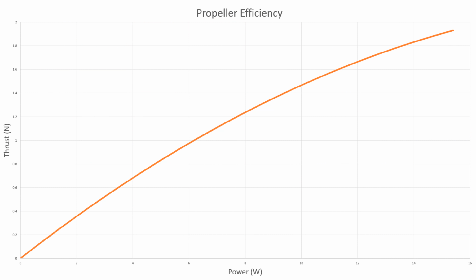And if we look back on the propeller efficiency graph, at low thrust values, it produces about 20 grams of thrust per watt. But at higher thrust values, it only produces 13 grams of thrust per watt. So as the thrust is increased, the propeller efficiency decreases, probably due to extra drag of the propeller having to spin faster. So what we need to do is produce the lightest possible craft that we can with a single turbine and a single plastic bottle.